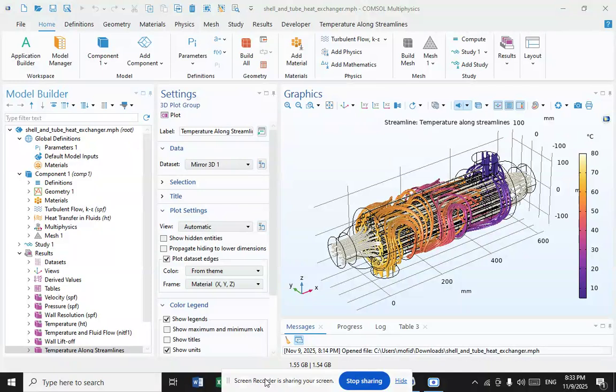And the next topic is tube pitch. When designing the tubes, it is practical to ensure that the tube pitch, for example, the center distance of adjoining tubes, is not less than 1.25 times the tube's outside diameter. A larger tube pitch leads to a larger overall shell diameter, which leads to a more expensive heat exchanger. Tube corrugation. These types of tubes, mainly used for the inner tubes, increase the turbulence of the fluids, and the effect is very important in the heat transfer, giving a better performance.